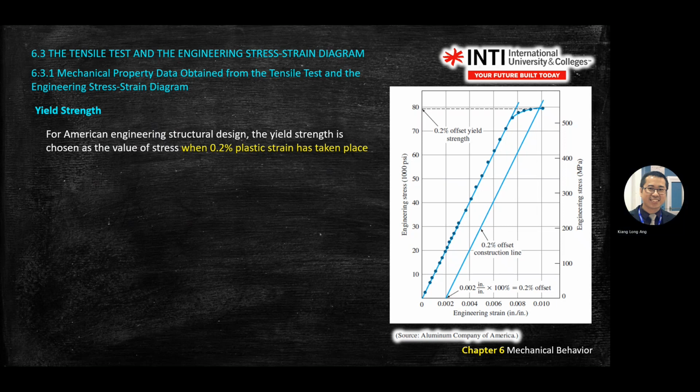You copy. Here, these two rows give you what is E, right? You can find E, because these two give you Y equal to mx plus C. You get the E already. Then you can replot the new stress and strain. Your stress will be the same, but the strain you can shift a little bit.